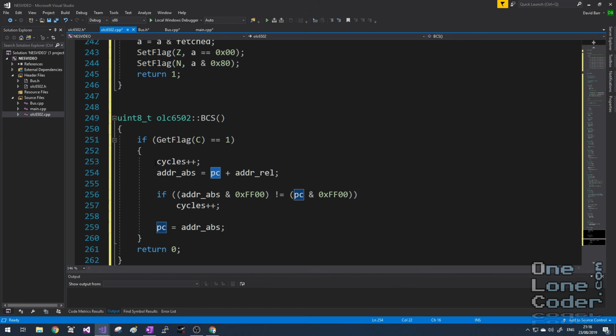Branch instructions are unique in that these will directly modify the cycles variable. When a branch is taken, that automatically adds 1 to the required number of cycles for that instruction. But in addition, if the branch needs to cross a page boundary, it incurs a second cycle of clock penalty. So branch instructions can potentially require 2 additional clock cycles.